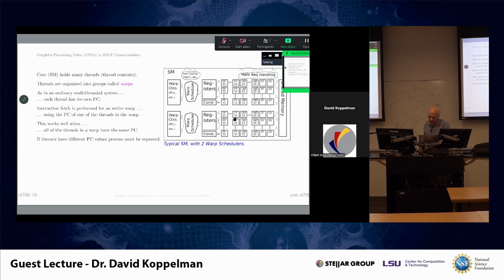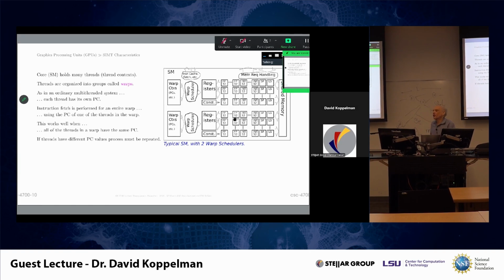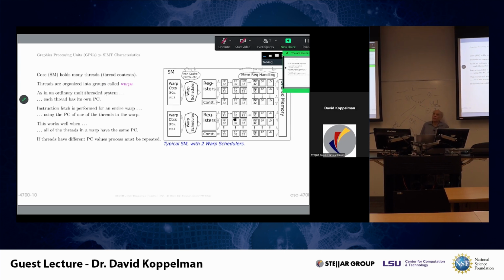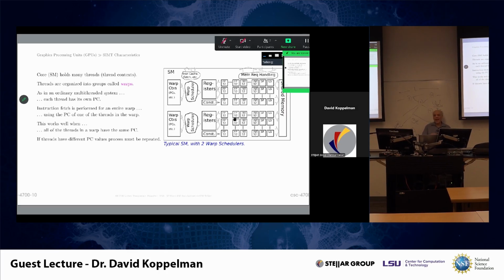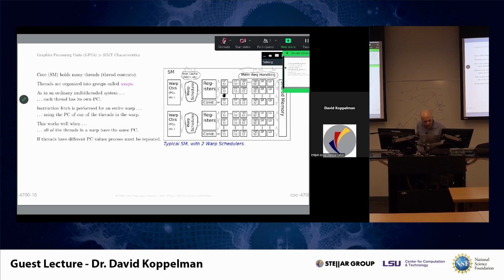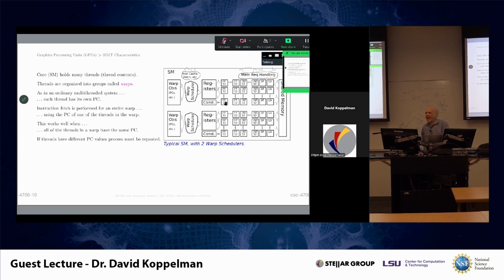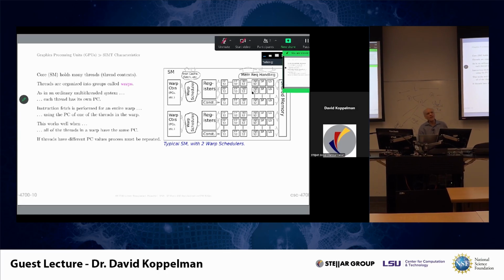Let's start at the bottom. This FP32 is a functional unit, and in the NVIDIA devices, that will do a multiply add operation plus related operations like multiply and add. Importantly, it does not do division. Division is done somewhere else. So here we have the multiply FP32 units, and also there are integer units. The number of integer units maybe is half the number of floating point units.